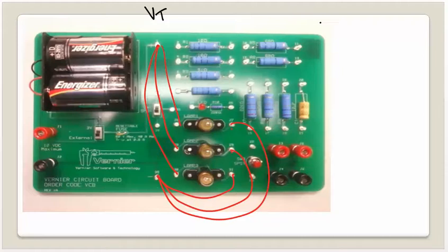If I want to find the voltage across any one resistor, well, that's not going to change. I'm still going to put my probes on the opposite ends of that resistor or light bulb. I'd put them here or here. This one here would be for V2. And then for V3, I'd put them there.